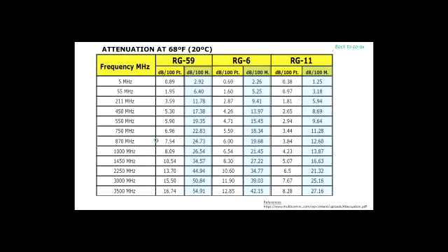Okay. So over here, okay, here it is. So at 5 megahertz, you can see that the one thing that's common to all of those is that the higher the frequencies, the more loss you get. Okay, the lower frequencies, they pump through with a lot of energy. They can carry through a long distance with little loss. Now, the problem is with the higher frequencies, they don't have as much energy, and as they travel through the cable, they get deteriorated quicker than the lower frequencies.